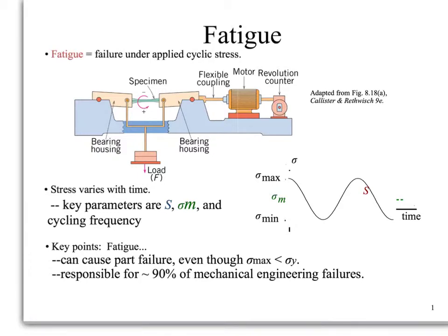Different types of load that fatigue can have include axial, which is tension and compression loads, flexural, which includes bending, and torsional, which is twisting. The plot shown below is a variation of stress versus time for fatigue failures, and it can be analyzed.